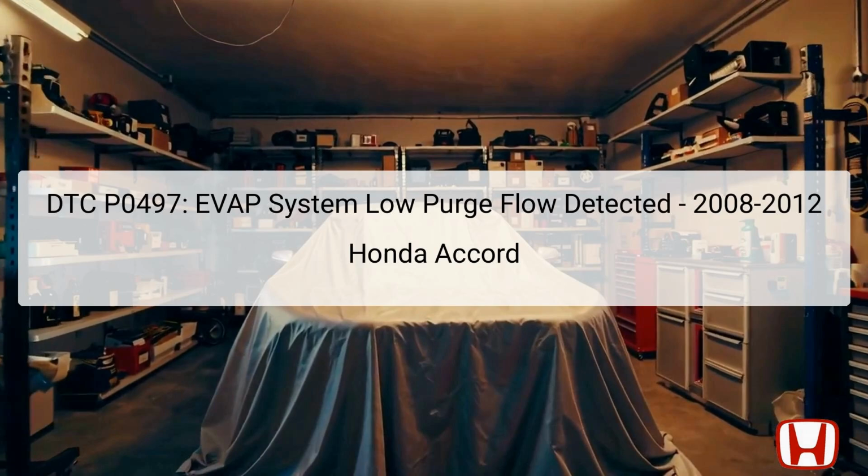The diagnostic trouble code DTC P0497 indicates an issue with the evaporative EVAP emission control system in the Honda Accord models from 2008 to 2012. Specifically, this code suggests low purge flow detected, meaning there is insufficient vapor flow from the EVAP canister to the engine's intake. The EVAP system plays a critical role in capturing and reusing fuel vapors, helping to minimize harmful emissions.